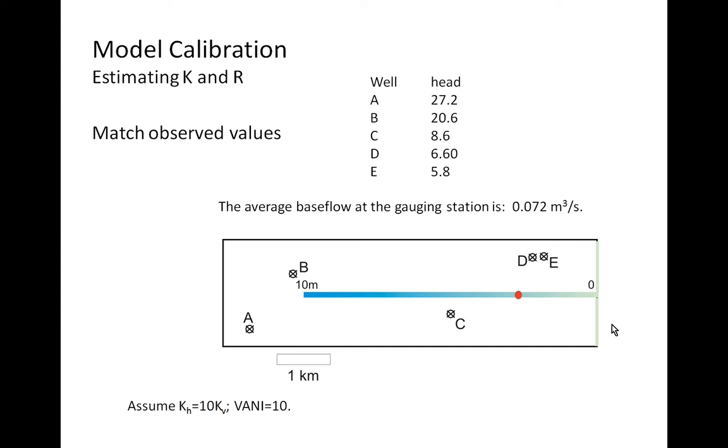Typically, if we have a model that looks like this, our idealized alluvial aquifer, we have observations that consist of hydraulic head measurements at monitoring wells. Here are these 5 monitoring wells as an example, and often they'll be stored in a table, where each row is the value at a certain well at a particular time.